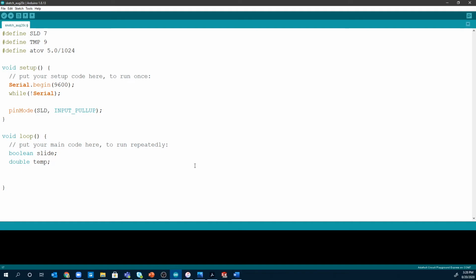To do this, we can simply use the character array style string, which we've discussed in the early lessons. We will need an output variable where we're going to store our final result. This will be a string. Note that Arduino can handle 2 types of strings. It can handle a C style string, which is what we will be using in this course, or it can use a C++ style string, which is slightly different.